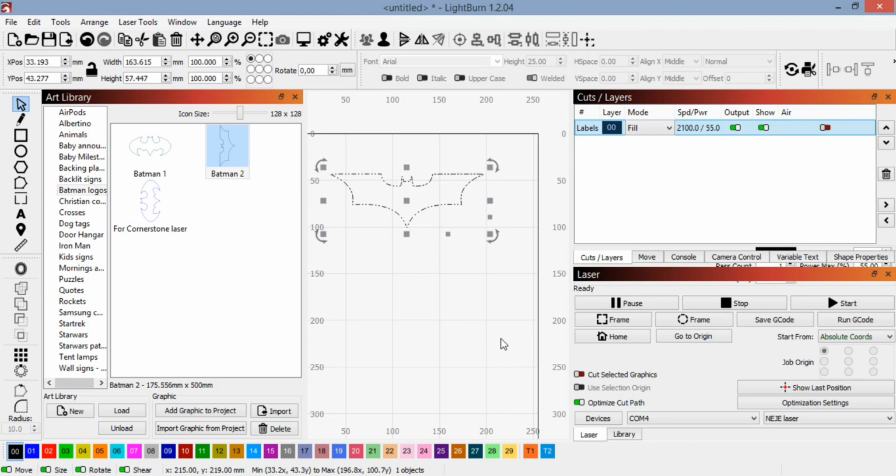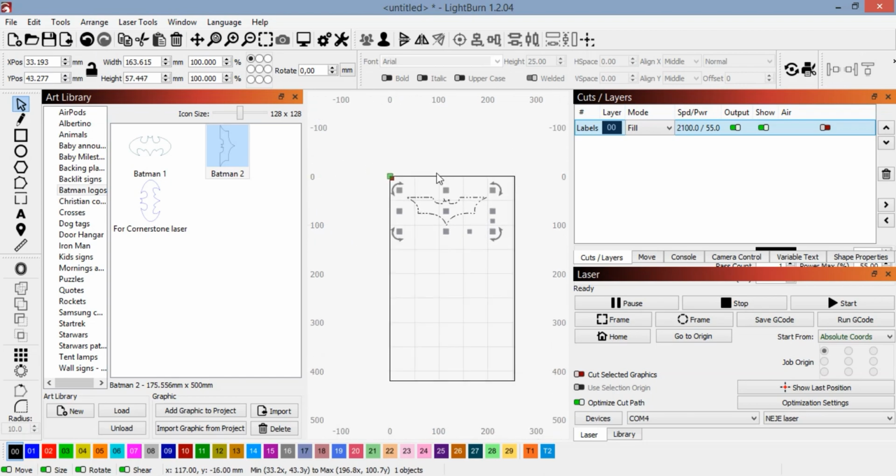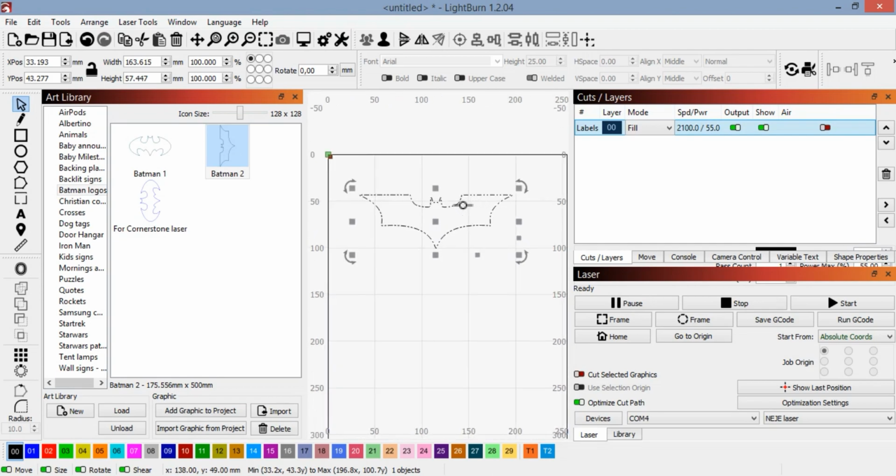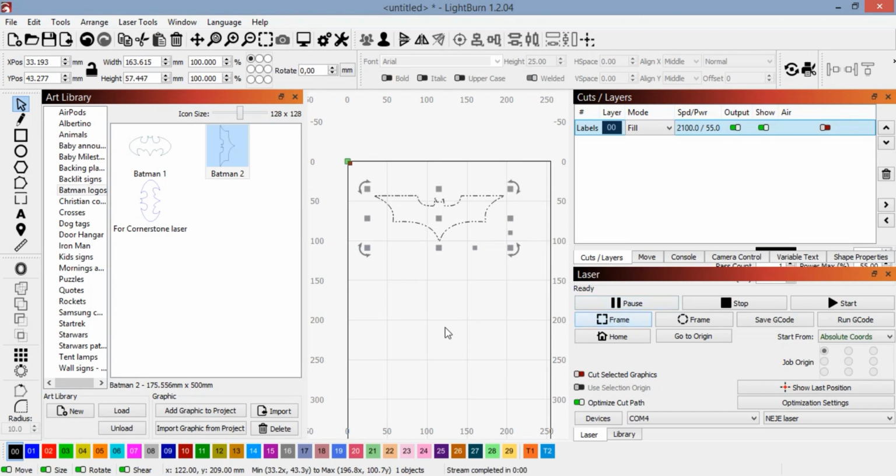There's quite an amount of information to understand there, but basically you can see my work area is right over there with the grid lines, which are actually engraved on the base of my laser station. And so I'm just going to frame it. What that does is it ensures that you're going to be lasering exactly where you plan to. There are other ways that you can set this and really easily align this to a workpiece, which again I'll do in a later video. It does take a bit of understanding, but it's super simple to do this and get repeatable results.